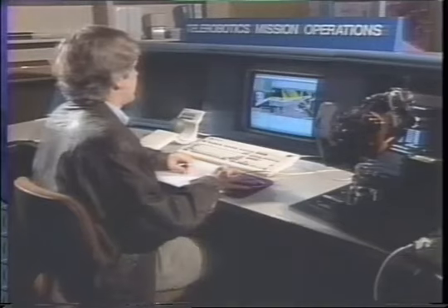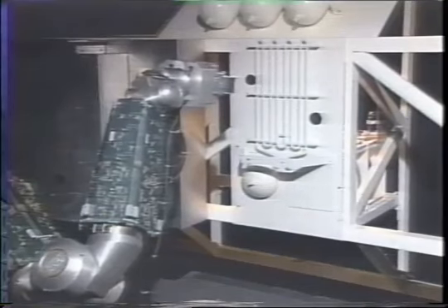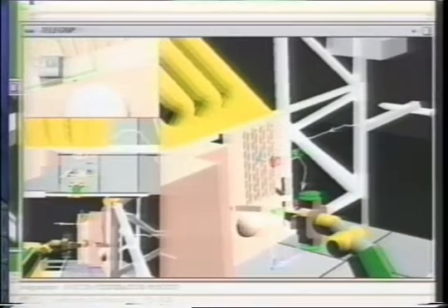When the operator initiates the scan, the robot follows the motion guide. When the robot arrives at a location which has one or more icons, then the subtasks associated with the icons are executed. When the subtasks are complete, then a camera is automatically pointed at the next position which has an icon. If an automated visual inspection subtask detects a flaw, then the camera icon at that location is turned red. Otherwise, it is turned green. If a temperature anomaly is detected, then a red thermometer icon is placed at the temperature anomaly location.